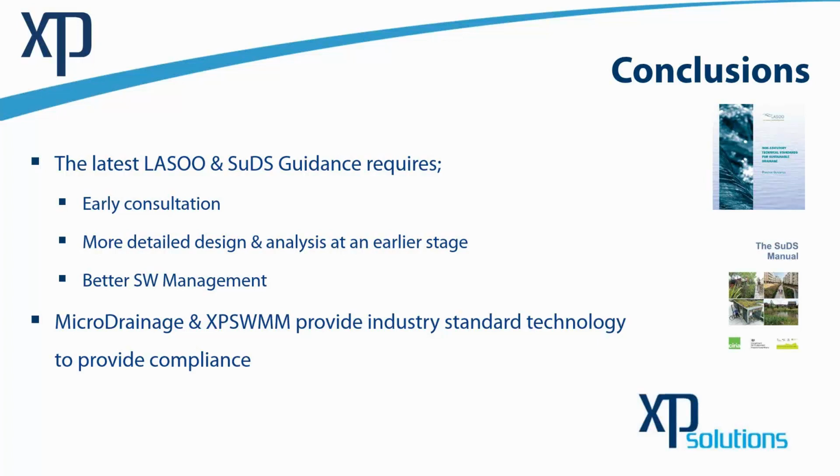We're looking at the long term now. So what are the consequences of things flooding, whether that be from the catchment or from our development, going way beyond the design? Are we in a good state to manage that surface water? Have we taken the overland flood routes into consideration?